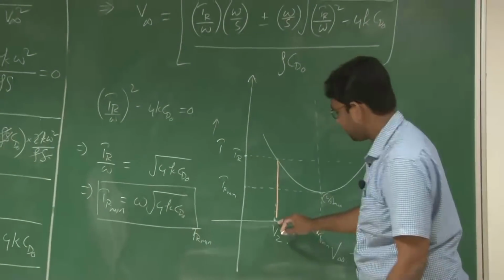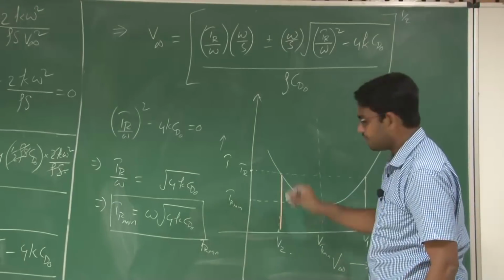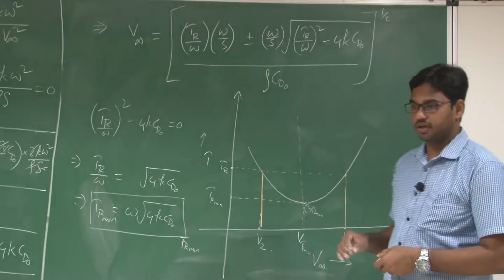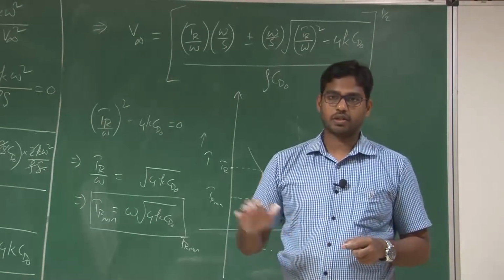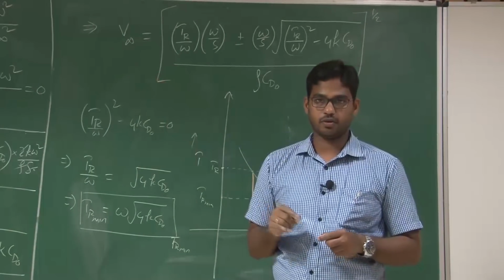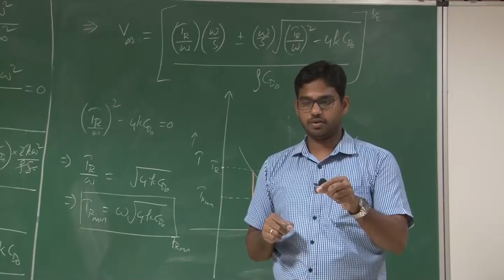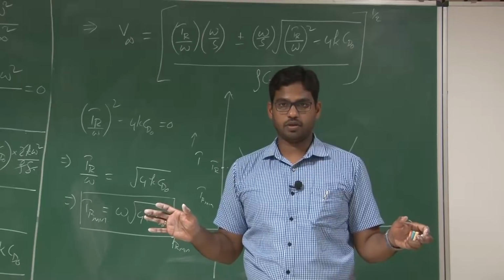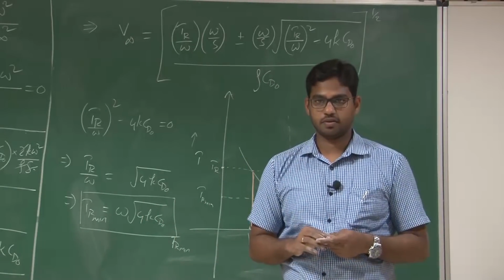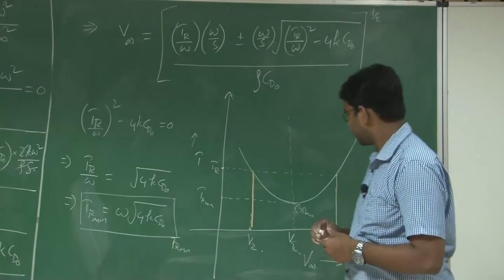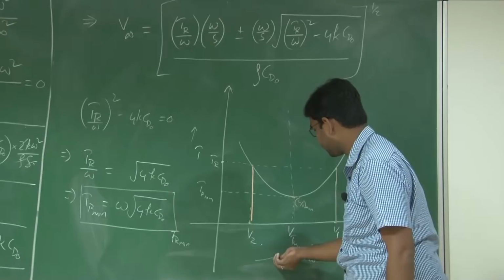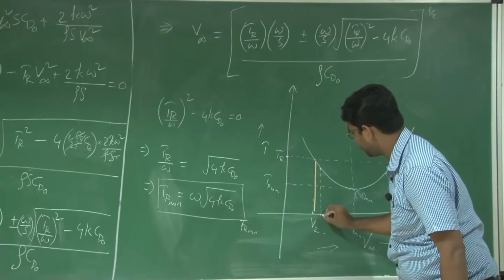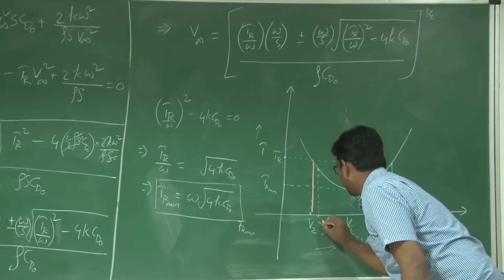Now let us consider velocity V2, right. During this discussion, let us assume the pilot from the ground station has set the throttle of this UAV to a particular setting, has trimmed the UAV to a particular throttle setting. Now we are not controlling the UAV, right. Now say there is a sudden gust which has increased the velocity. Now say this is the direction of increased velocity. This increase in velocity will take you to this point. Let this be V2 prime.